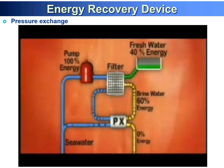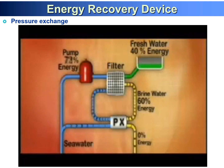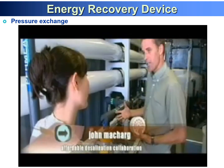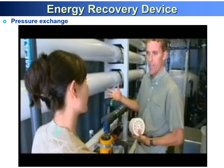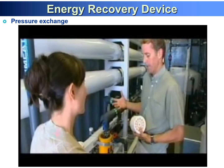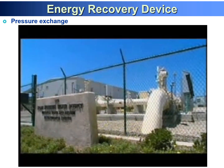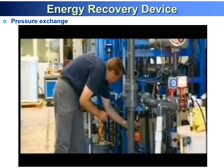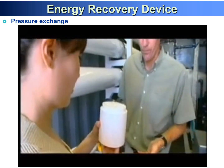Californian company Energy Recovery Incorporated finally cracked the problem with a device called the PX pressure exchanger, which cut energy costs by a massive 60%. So what the pressure exchanger does is it recovers the energy in that waste stream at almost 100% efficiency. It operates at 97% efficiency, which in engineering terms is extremely efficient. John McHarg heads up the Affordable Desalination Collaboration, a US Navy joint project with the Bureau of Reclamation. For more than a year now, they've been testing and evaluating the latest desalination technologies, including the pressure exchanger.